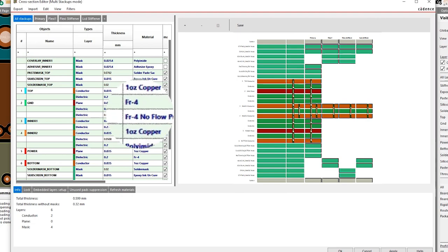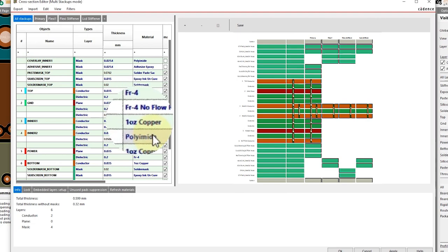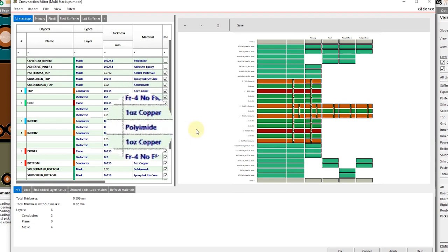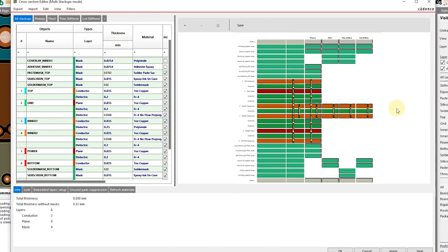And then for the internal layers, which continue into the flex region of the board, they are of the type polyimide. So careful selection needs to be done when defining your stack up, right? And it's often an iterative process in collaboration with the PCB vendor that you'll be fabricating with, and they'll help you in guiding how to select appropriate materials, copper thickness, any kind of trace requirements you have for routing, right, impedance constraints and so forth.